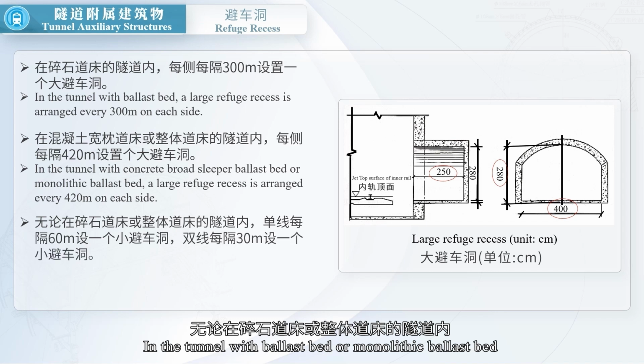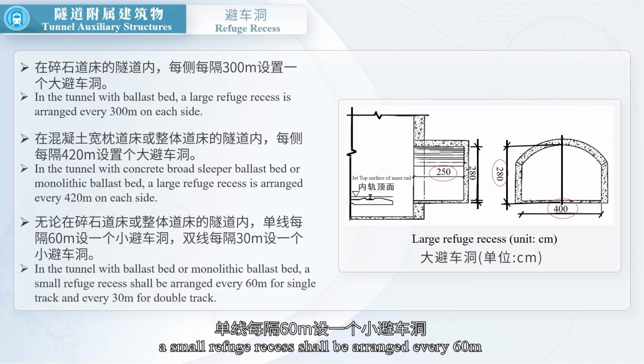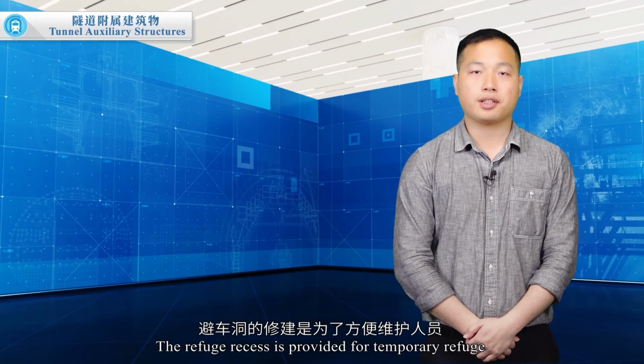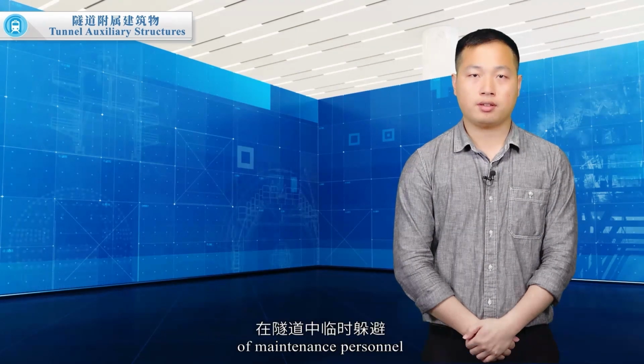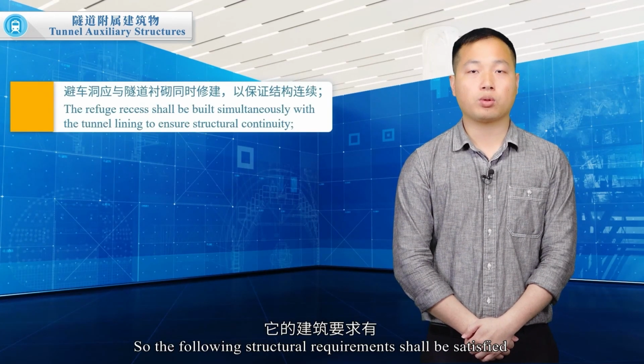In the tunnel with ballast bed or monolithic ballast bed, a small refuge recess shall be arranged every 60 m for single track and every 30 m for double track. The refuge recess is provided for temporary refuge of maintenance personnel. So the following structural requirements shall be satisfied.